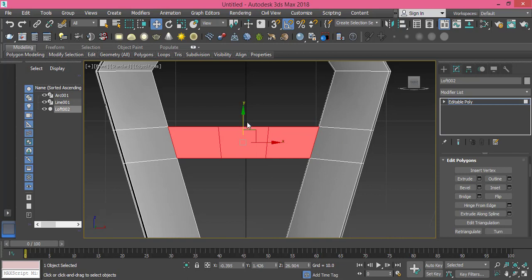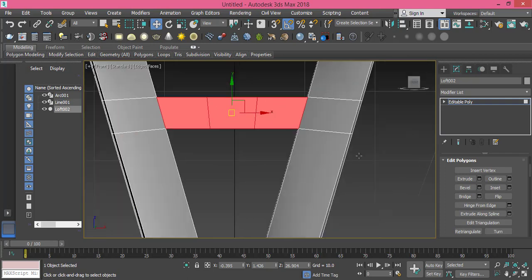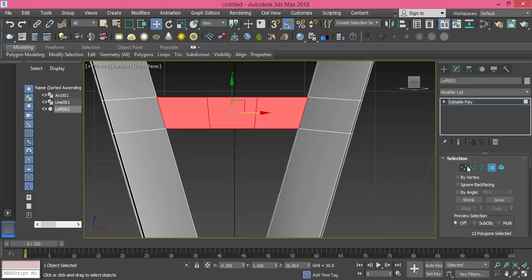Now if I want to make extrusion here, see we have these non-diagonal angles. We need to make them diagonal, so we change the mode to vertex mode and we select this guy. We go to scale, and on the x-axis I'll scale as much as I can to make them straight. Same for this guy, and then I select both of them, and on the x-axis I'll make them as close to each other as possible. Okay, that's fine for now.